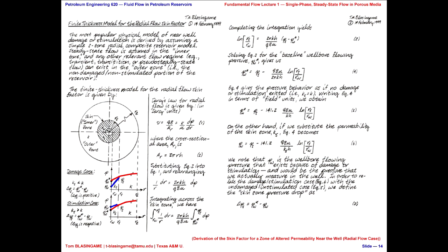Is this a real equation, class? Can you calculate the pressure at point PS using the pressure at the well? Well, yeah, you can, but you have to know the permeability and you have to know the distance. So that's what we call an indeterminate relationship. We would have to assume that the distance that it propagated out in the formation is 1 foot, 2 foot.